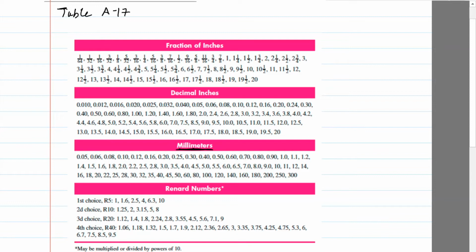These are all diameters, so we need to go through the diameter and see if 112.8, 113 is available. If you go here, you'll see that unfortunately that's not available. It's basically somewhere right here. So either we can buy a 100 millimeter diameter shaft or a 120 millimeter diameter. Now the question is, which one would you choose? 120. Why? The reason is because